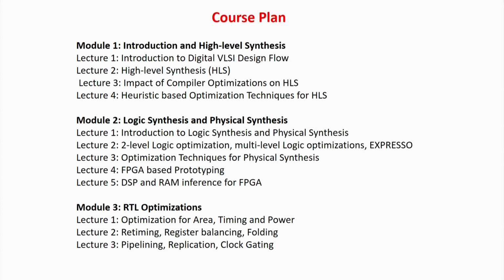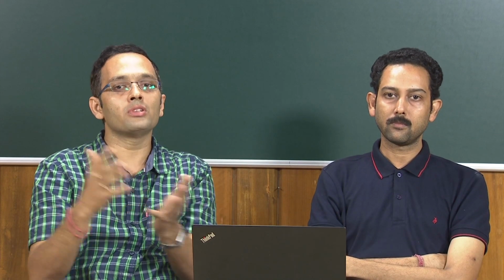We'll briefly cover that obviously, but what we're going to give more emphasis to is how we can use high level synthesis effectively. It means suppose you start high level synthesis from a C code. What would be your C code, right? What is the good way of writing C code so that the hardware that we're going to generate out of it will be efficient in terms of timing, power or area, right? It's not that all C will give you the same hardware. So you have to know which is a good C. The way of writing C is important, so we'll emphasize that part.